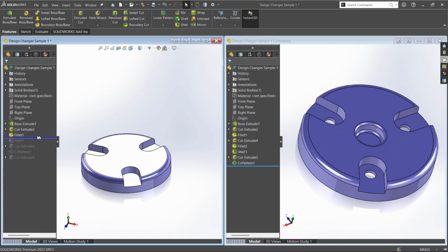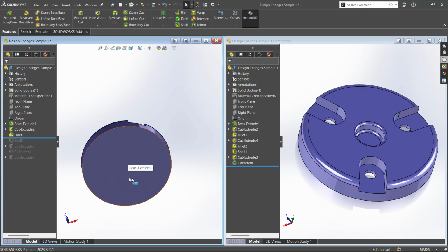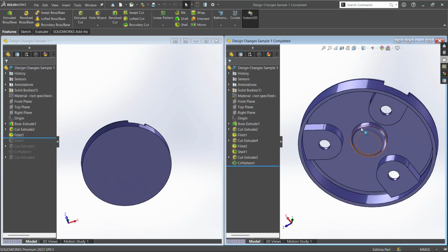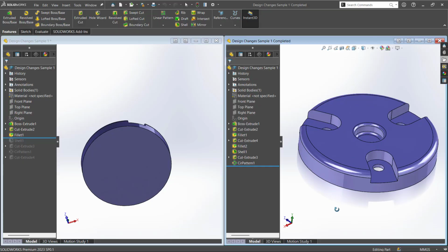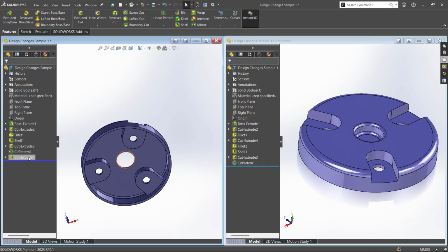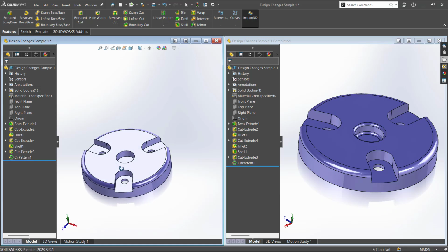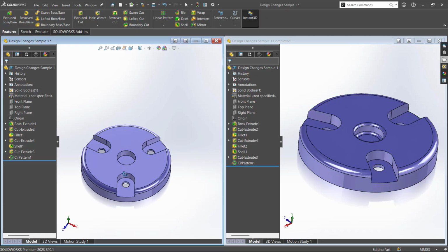Even if I just keep it here, this is a fillet, and here also if I create that particular cutout, there won't be a direct hole as it is now, right? So what I need to do is create one particular cutout here, so that the shell feature can recognize this cavity and assign the thickness for this. So instead of recreating, just drag and drop it here. Okay, now you could see I simply dragged and dropped it here.